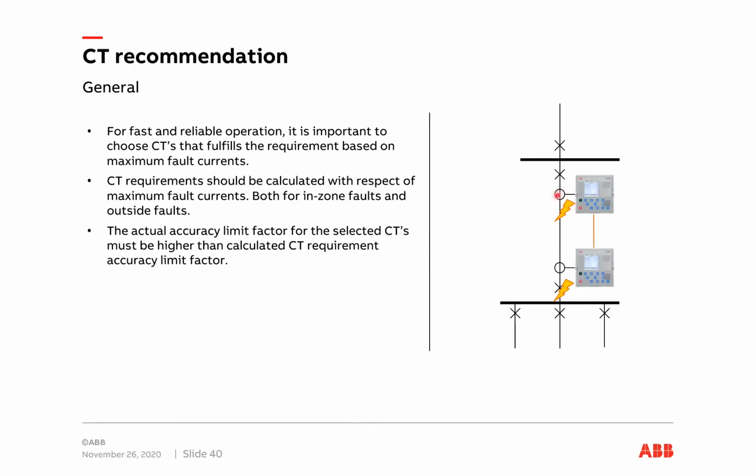So we need to calculate it both for inside faults and for outside faults. And with these fault currents, we can then calculate the accuracy limit factor as a requirement for our CTs.